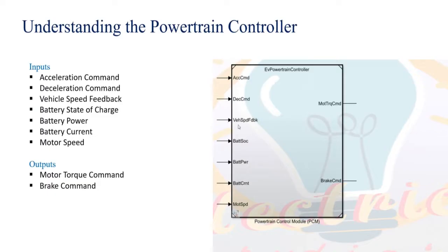We have some wheel speed sensors on all our 4 wheels, and these wheel speed sensors determine the vehicle speed at any point of time, and that is also an important input to the motor controller. And what else do you need? Is that enough? No, not enough. You need to know the motor speed as well. Currently, what is the motor speed? Either the motor is running or not. So how to determine the motor speed? You know, using the sensors, right?